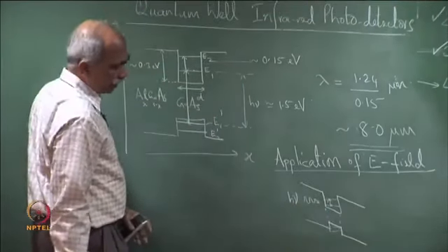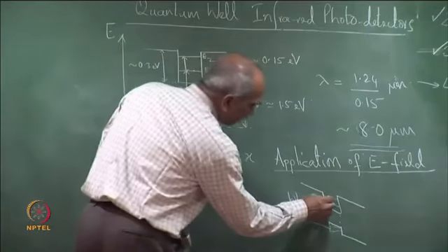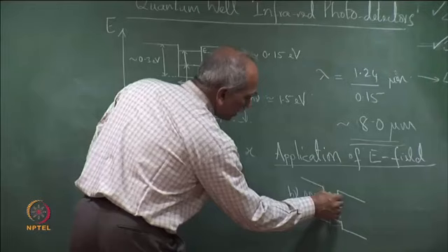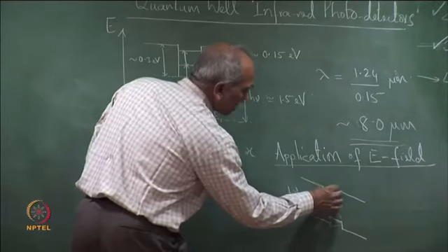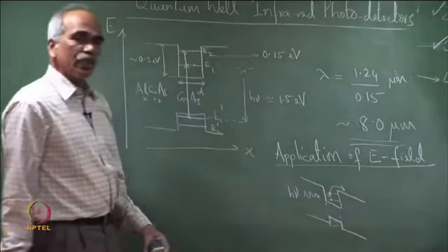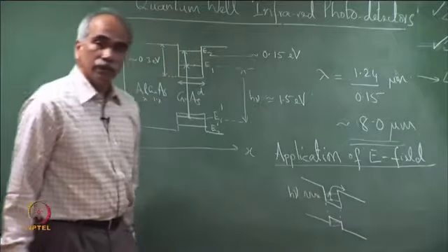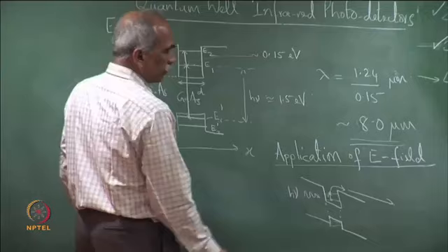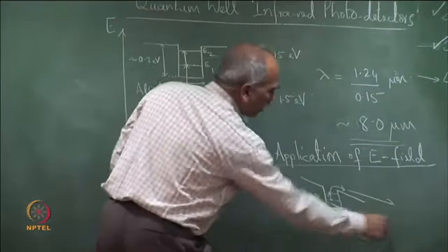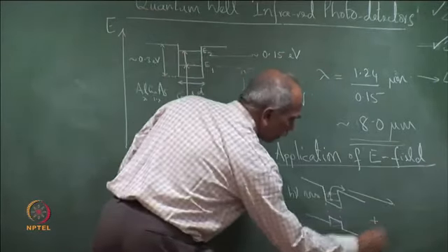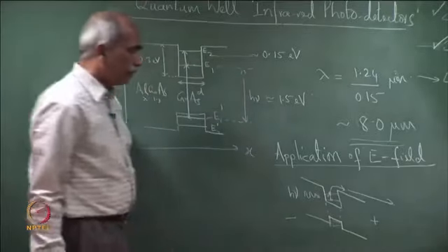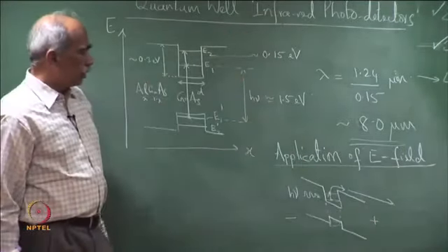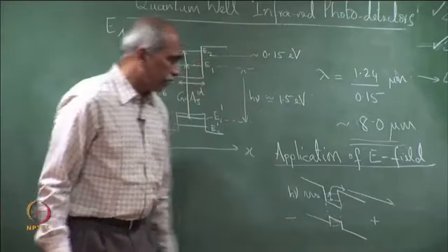to this level here. Because the potential barrier is now much smaller, the electron can spill over, that is thermionic emission over the barrier, and then it will be swept to this end. The electron will be swept because there is an application of electric field. This side we have applied a positive and this side we have applied negative. So, the electron will be swept to the electrode where we have applied the field.